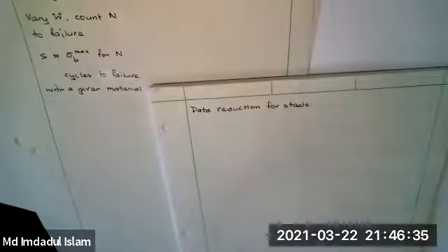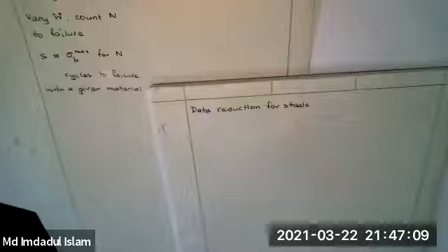It's going to turn out that there's a wide variety of N. N varies by orders of magnitude. I don't know if you remember this, but up to 10 to the 3 or 1,000 cycles we call it low cycle, and above 10 to the 4 we call it high cycle, and between 1,000 and 10,000 is somewhat debatable. Some people call it transition. We're going to lump it in with high cycle. And after you start getting to 1 million cycles, it's pretty standard in steel to regard that as indefinite life.